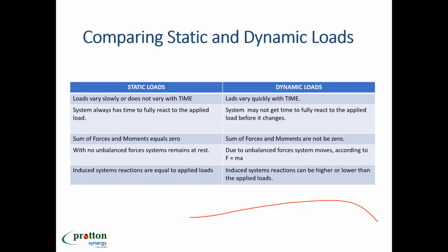In static analysis, the sum of forces is zero, what we have learned: summation Fx, summation Fy, summation Fz are zero. And that is the reason when you do a static analysis, you will find action and reaction. So in stress analysis, if you find a load on a pump, you check the support in front of the pump, suppose a guide or a stop or a guide after the line turns, whether you are getting an opposite sign load. Then you come to know that this guide is creating a problem, you increase the gap or you remove it. But this fundamental is not true for dynamic analysis.